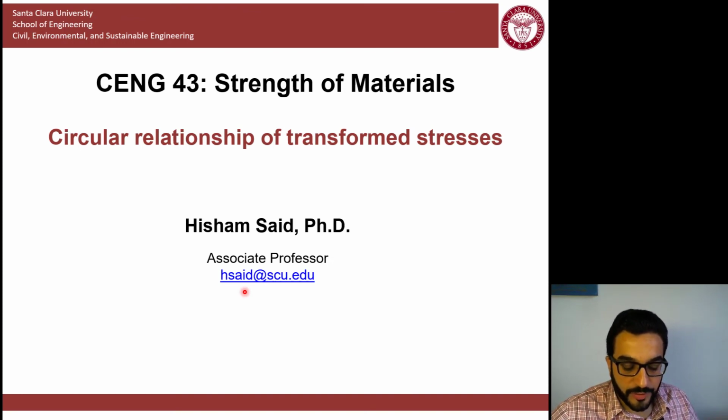Mohr circle is a very, very important tool, and it's very fundamental when you move to advanced classes in strength of material, machine design, and structural analysis, to understand the development of stresses at a point. The orientation you choose to analyze or calculate internal forces and internal stresses at the point doesn't mean that this is the orientation that the failure will happen. You have to figure out the orientation of principal stresses and the orientation of maximum shear stresses.